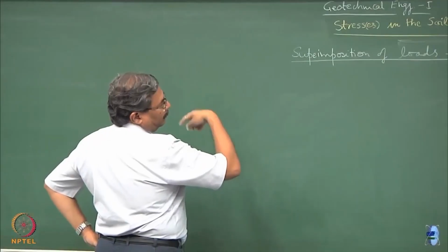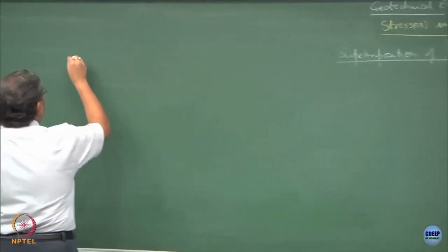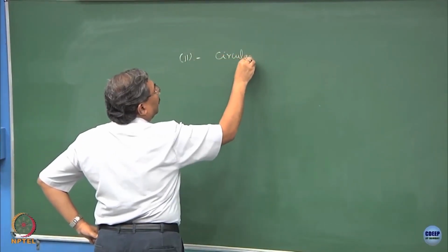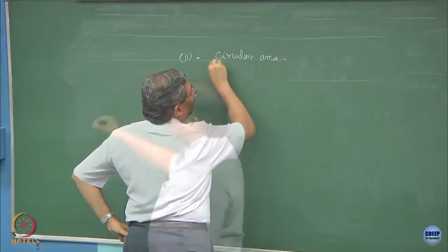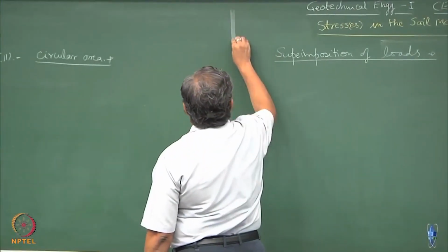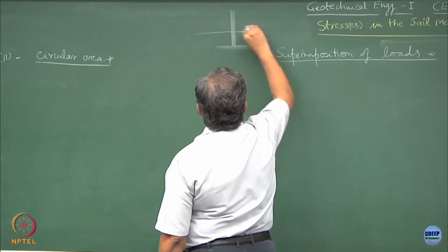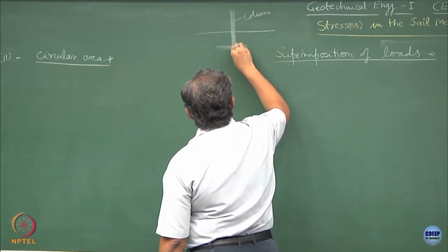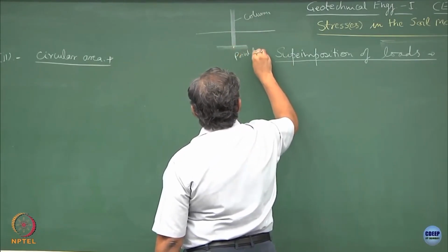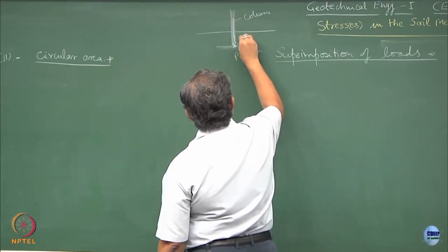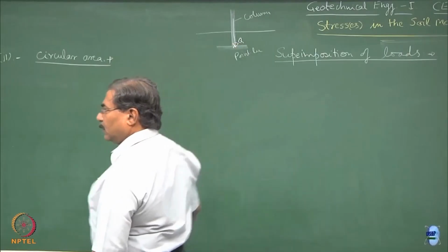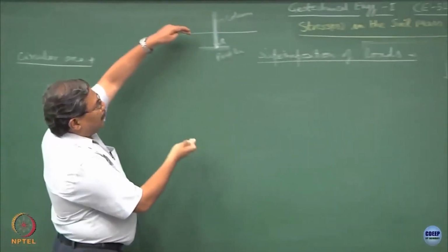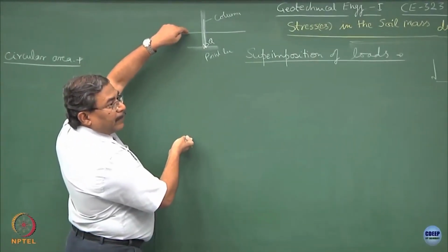the second situation, from point load we will move on to the uniformly distributed circular area. Until now we have talked about a foundation system, where this is the column. So, this is the point load. The best possible approximation would be that the Q is acting at a given point, though the foundation also is of finite size. But this is an approximation as compared to the domain of semi infinite soil mass. Clear?